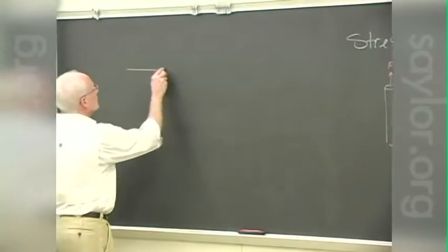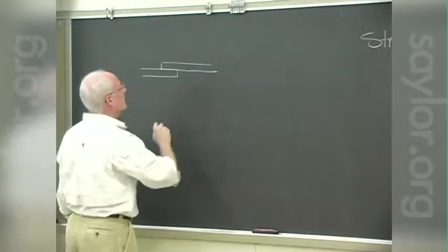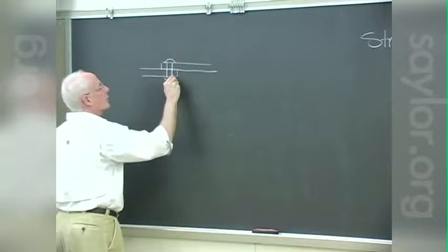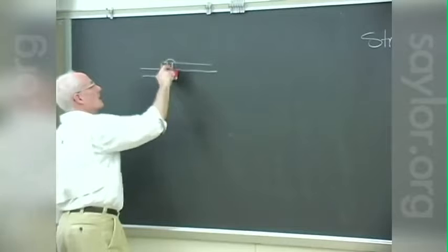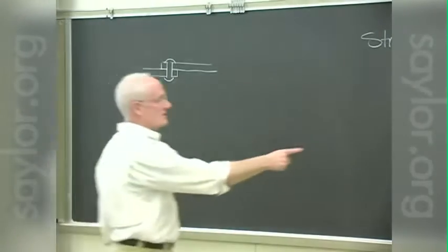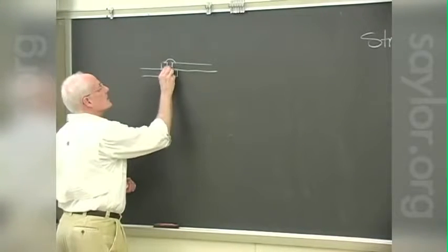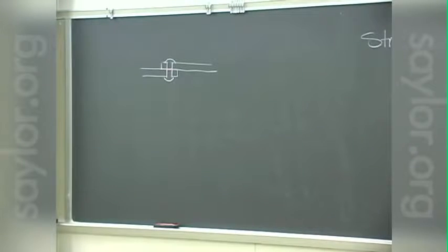But if we look at two members that we've pinned together, we're going to do it by probably putting a rivet or a bolt or something through the piece to hold those two structural members together. That pin itself then is under these shear forces, where the area of concern is right there where the maximum amount of the shear is occurring.